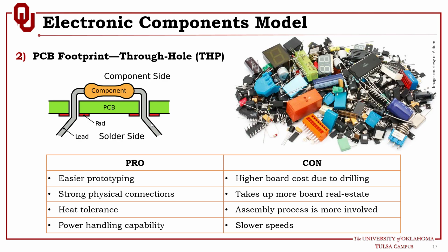And if you go online and try to request a quote for PCB assembly, they will ask you how many through-hole components you have and how many surface mount components you have, and what is the size of each. And the through-hole component will add significant cost to the assembly quote, because it requires some kind of manual process. And also slower speeds when it comes to signal integrity. It's not recommended to use through-hole components at all.